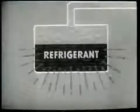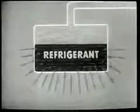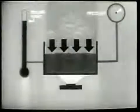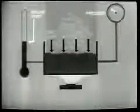The principles of refrigeration are physical principles applied as follows for the purpose of removing heat and reducing temperature. First, mechanical refrigeration rests on the ability of a refrigerant to absorb heat while changing from a liquid to a gas, and to release that heat while returning to the liquid state. Second, when the pressure on a liquid refrigerant is reduced, the liquid boils at a lower temperature. Third, the transfer of heat from food items or other warm surroundings to a liquid refrigerant involves three processes: